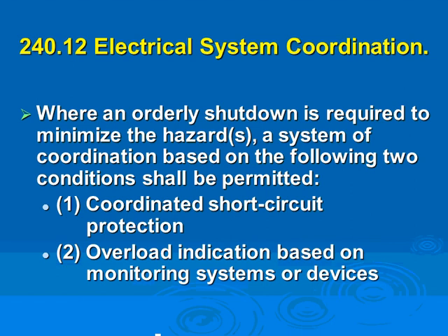If you have an emergency panel feeding fire pumps and elevators, and you have multiple elevators on the same feeder, by code you're required to have an overcurrent protection device. I'm saying required by code. Now, every engineered project that we do will do it, because that's above and beyond. And now, 70E requires you to have an arc flash label and an available short circuit on every main, right? The 2011 NEC requires every service panel to be labeled with the available short circuit right at that panel.